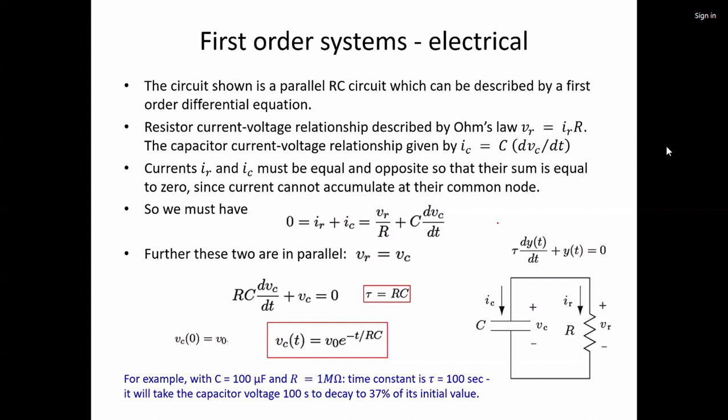Yeah, that is why when you want to change your input instantly and you want to measure the output instantly, you have to use a temperature probe sensor which should be fast enough, right? So the time constant of the instrument has to be very, very small. Okay. So you are saying that you are going to change the input every second, and you want to measure also every second. That means the time constant of the system should be very small, right? Maybe 10% of 1 second, maybe 0.1 second, or even smaller. Right. Thank you.